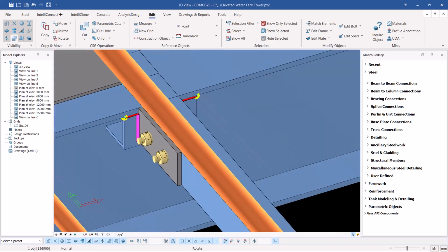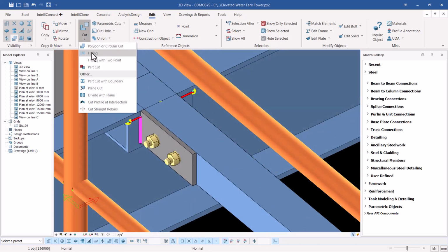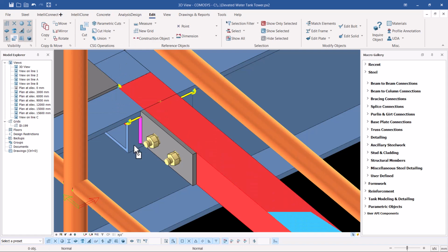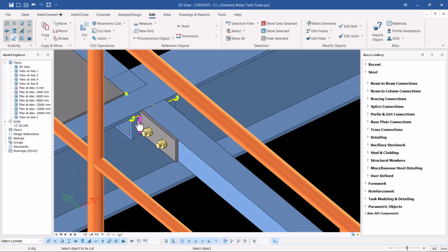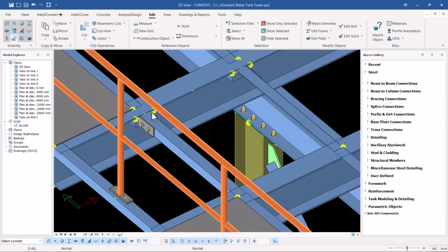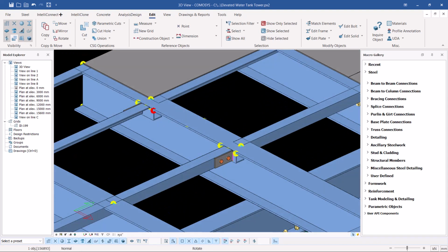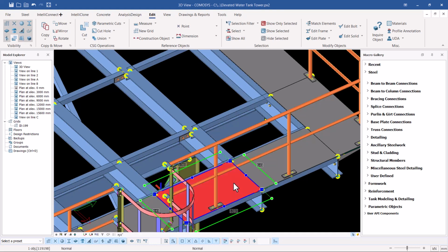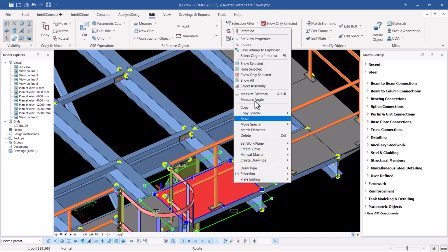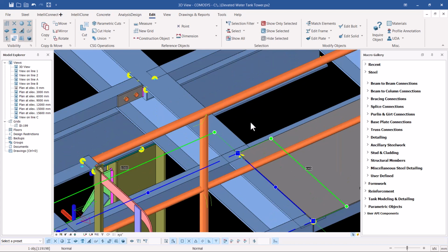Let me just turn it around and redo it. I'll come to cut, then pick on the fitting, pick on that, then pick the surface you want to fit it onto. Then I'll pick on that spot. So the fitting has taken place. So let me just turn that around and do the same thing here. On the other hand, I want to do the same thing here. I want to hide this so that I'll be able to see whatever I'm doing this far end.